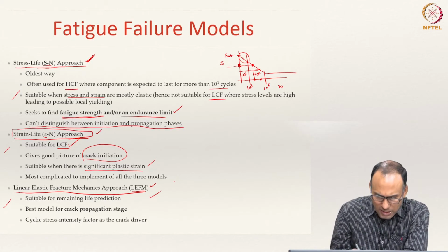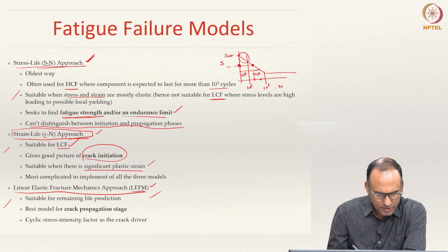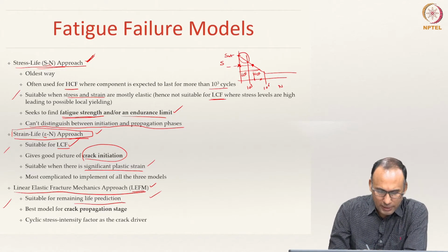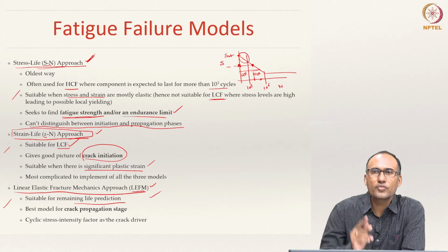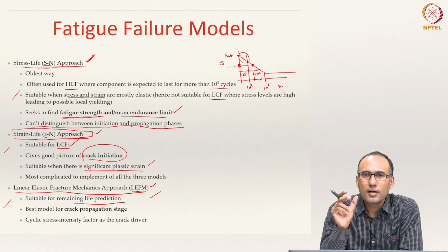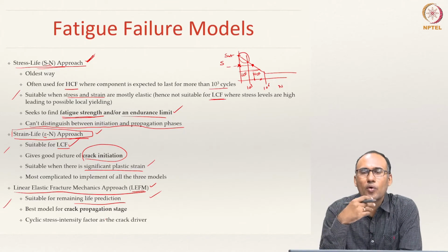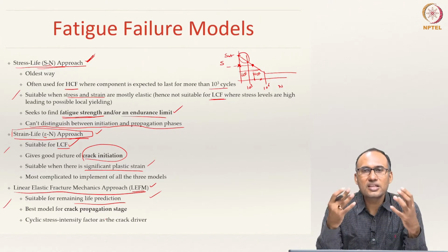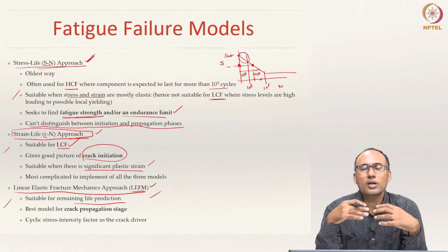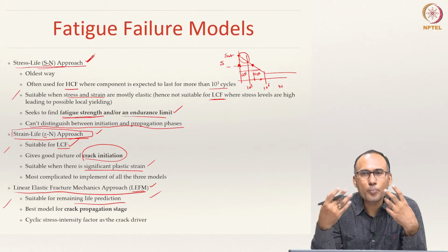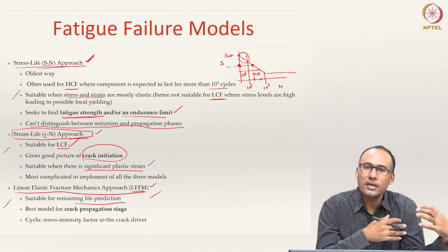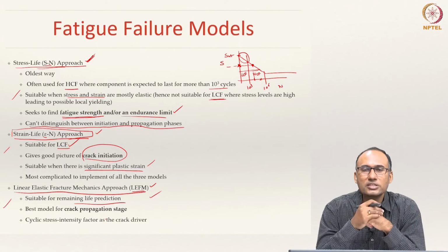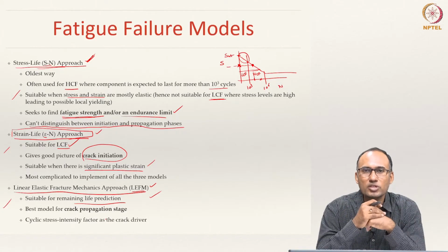And the last one is linear elastic fracture mechanics, and this is suitable for remaining life prediction. So, if you have a crack and you know the cyclic loading, can you predict how many cycles of life are still remaining? That means how many more cycles can I run this component for before actually replacing it. This is a very important piece of information for engineers particularly.